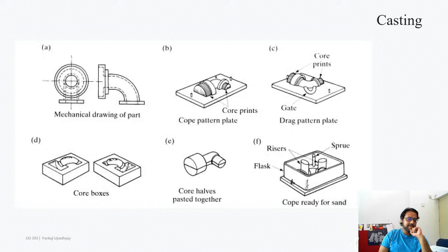Ace asks, I don't get this part. Won't the core touch the base and then ruin the structure? We'll see. Maybe once this whole thing is done. So let's first make just this internal cavity part. We made these two boxes, and let's say we joined these two boxes and made this small core. Okay, so this represents the hole that needs to be there within the part.